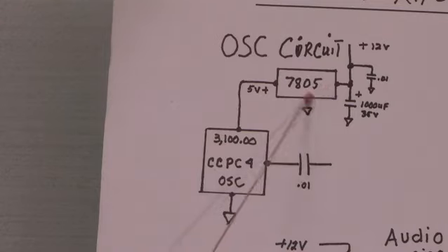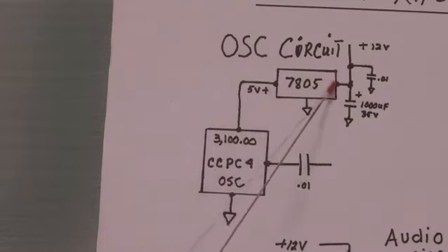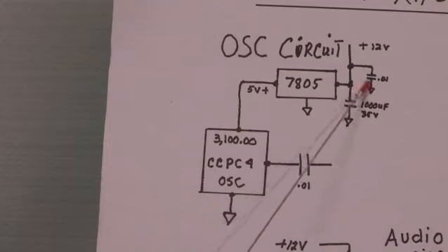And it's very important to remember with this type of CMOS oscillator, I think it does CMOS and TTL, that you regulate it to 5 volts, so you need a regulator in the circuit, and you can see that right here. And you need the filter capacitor here of 1,000 mics on the input from the 12 volt source. You want to keep this as stable as you can from the 12 volt lithium cells. And this is giving you your fundamental frequency in a square wave.